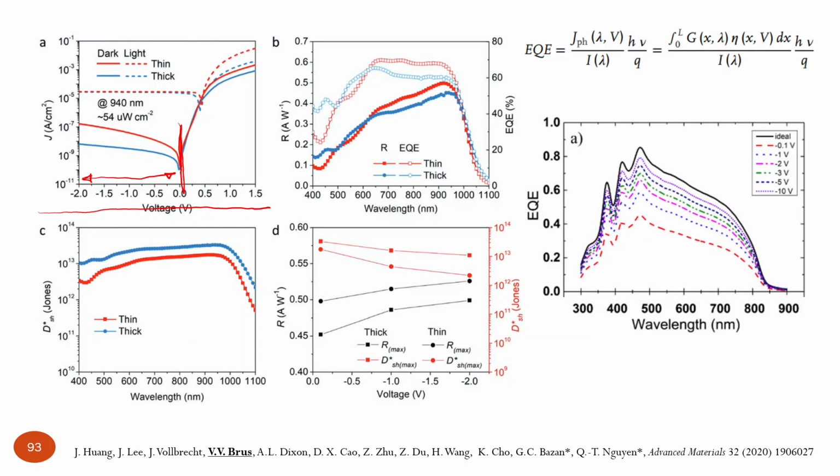So the next photodiode characteristic is external quantum efficiency. Here it overlaps with solar cells also, because it actually shows us in which spectral range it will be photosensitive. For instance, here we have this external quantum efficiency as a function of wavelengths. So we see that it's photosensitive from 400 up to somewhere 1000 nanometers. So what defines this long wavelength range, until which it is photosensitive? It's obviously the band gap of this active layer.